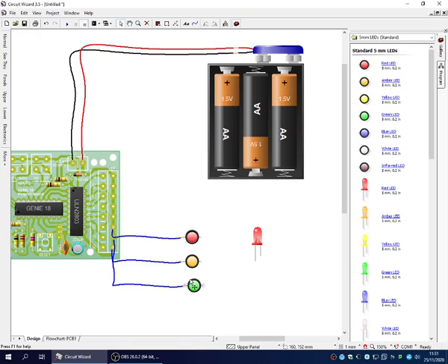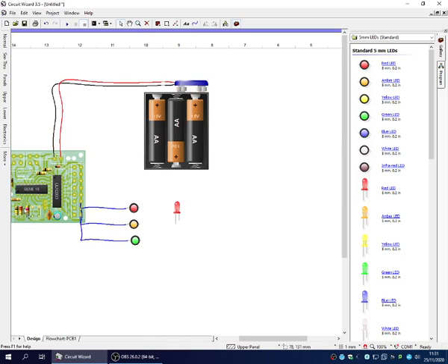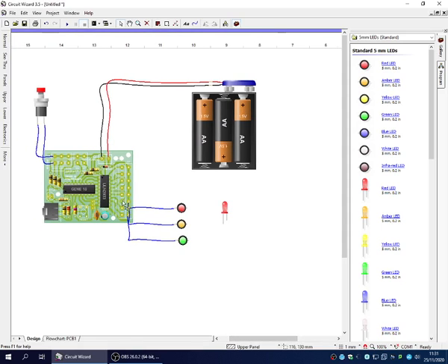Now, if you want to use LEDs, you're going to have to amplify the tiny little output and put your own individual transistors on the outputs where necessary. You might want to have bigger transistors than this bank of transistors. Say if you're using a motor or something like that, you'll want to have a bigger transistor than this. So it's good to customize your circuit. What you might be proposing in real life will obviously be a cheaper product if it only uses the circuitry it needs. It's going to be smaller. There's lots of benefits to customizing your own circuit.